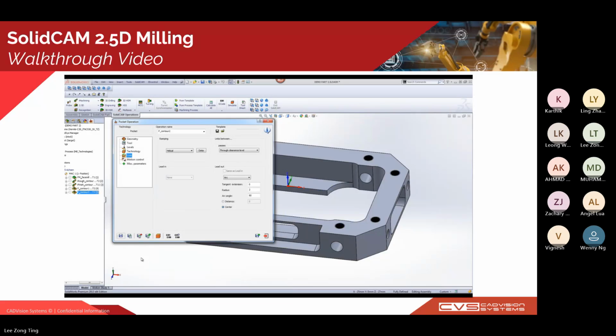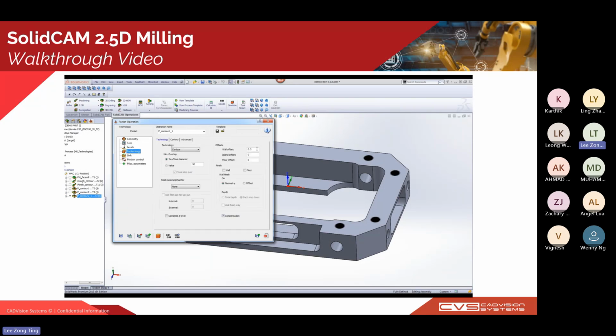So after that, what happened is I already did my roughings. So I want to do finishings using the same operation. I can directly save and copy, and you can see now I'm able to choose the roughing operation I'm using, which I am going to finish for. So I'm choosing pocket number 1, and I will remove the offsets